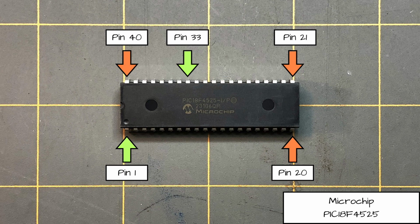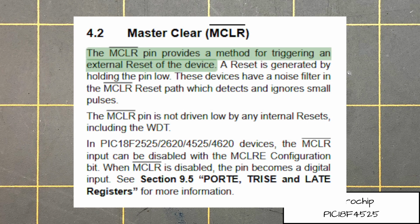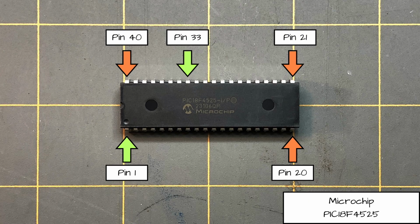Starting at pin 1, or the master clear pin, this will be used for our reset switch, or switch 3. If we were to look at page 43 of the data sheet for the PIC 18F4525 microcontroller, we'd see that this page explains what the master clear pin is for. The datasheet states that the MCLR pin provides a method for triggering an external reset of the device. A reset is generated by holding the pin low.